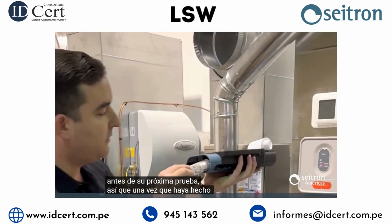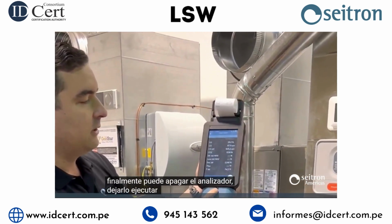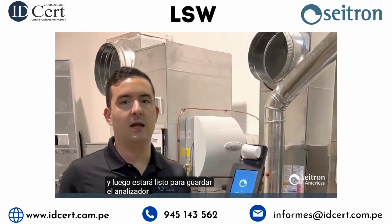So once you've done all of that, finally, you can turn the analyzer off, let it run through its final purge cycle, and then you're good to go to store the analyzer for your next test.